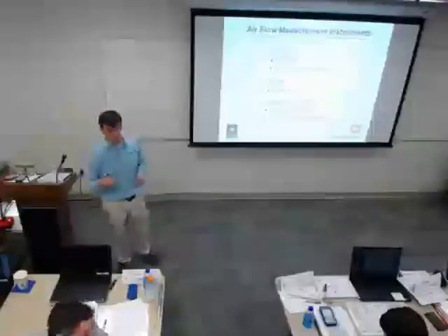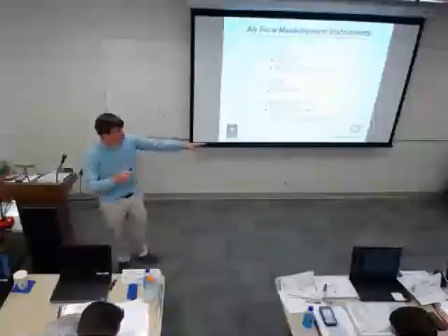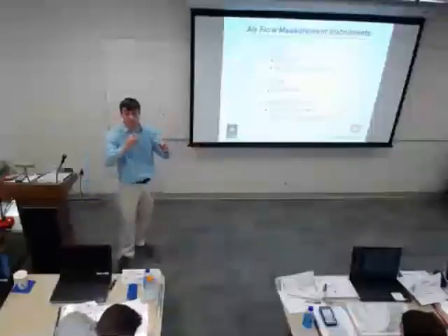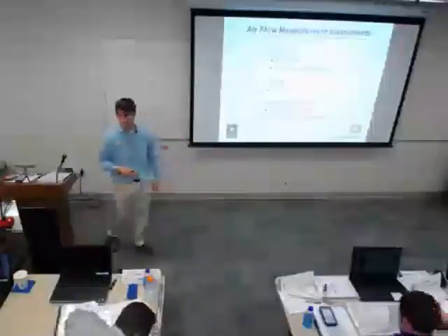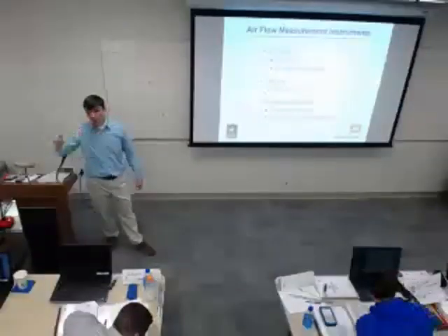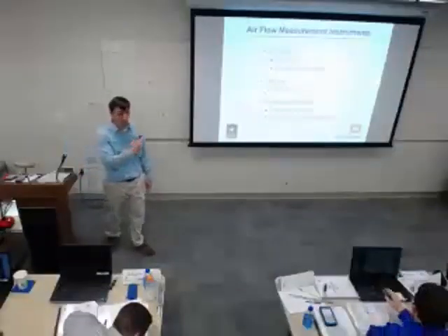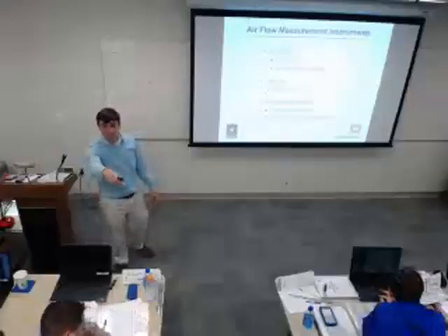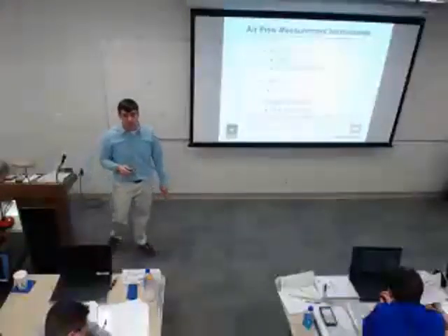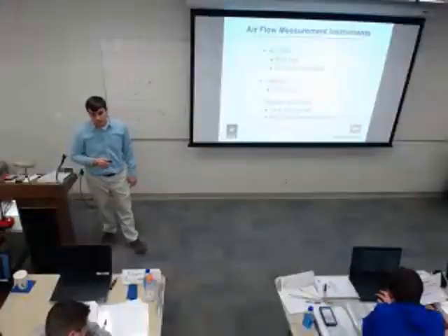If you don't have a good place to do a traverse, you might have to go in and use that all the way across a coil on an air handling unit to come up with the velocity. You're going to take multiple points to get an average across it. Question: is that a multiple point with an average? Yes.